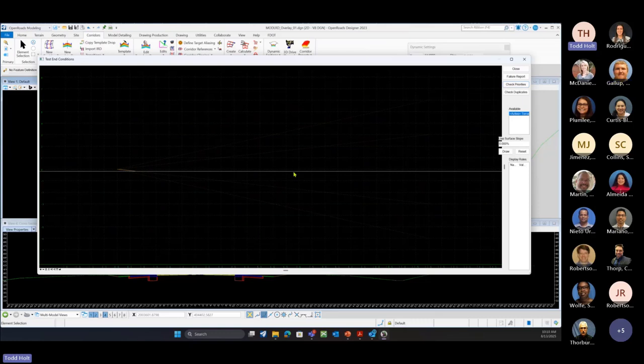The other thing on that, though, it could be set on your terrain, because it's the existing ground. On this example, it's just looking at cut and fill. It's just looking for the existing, but it's going to go and try and triangulate and solve for that. So if your terrain model is a big terrain model, you have extra, say, triangles outside of that terrain model, it's going to have to go run through and search that entire terrain model.